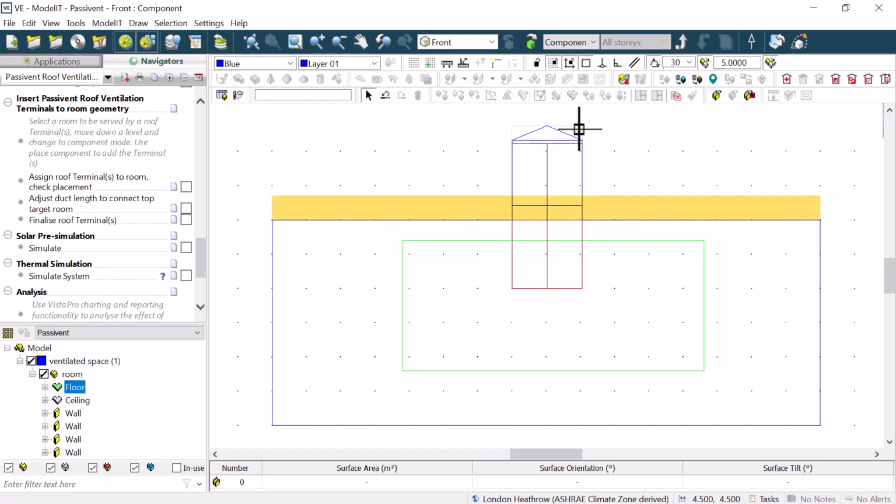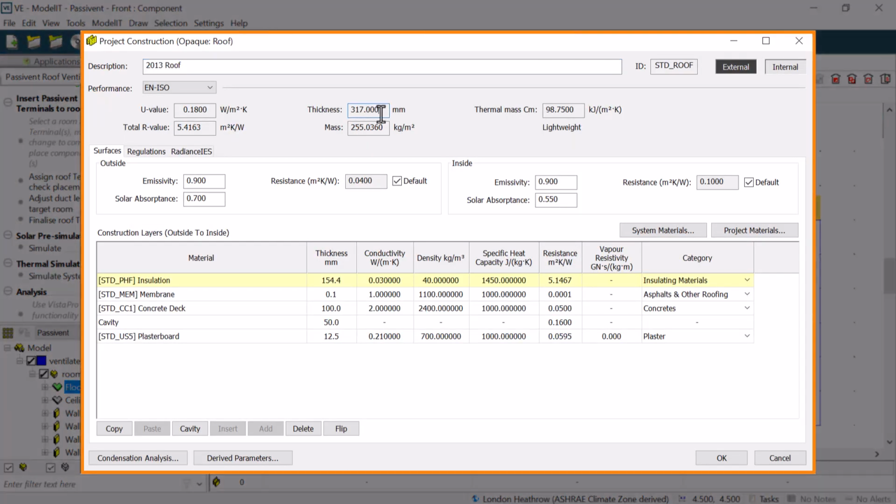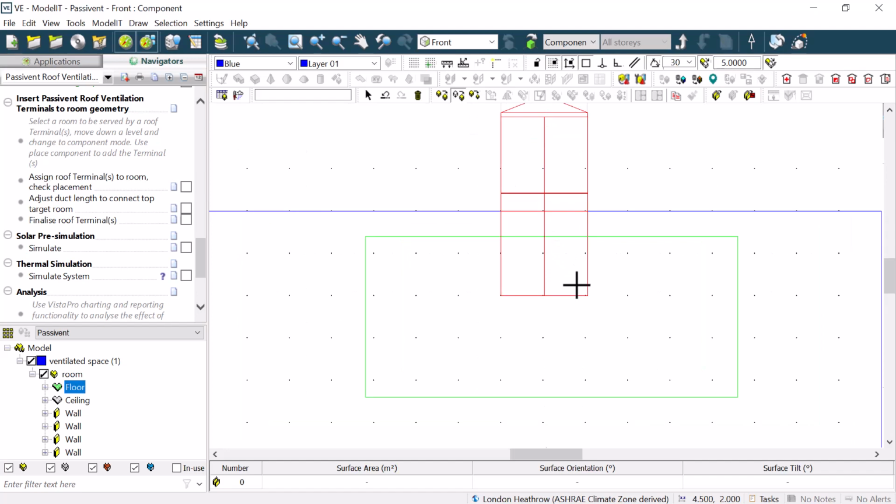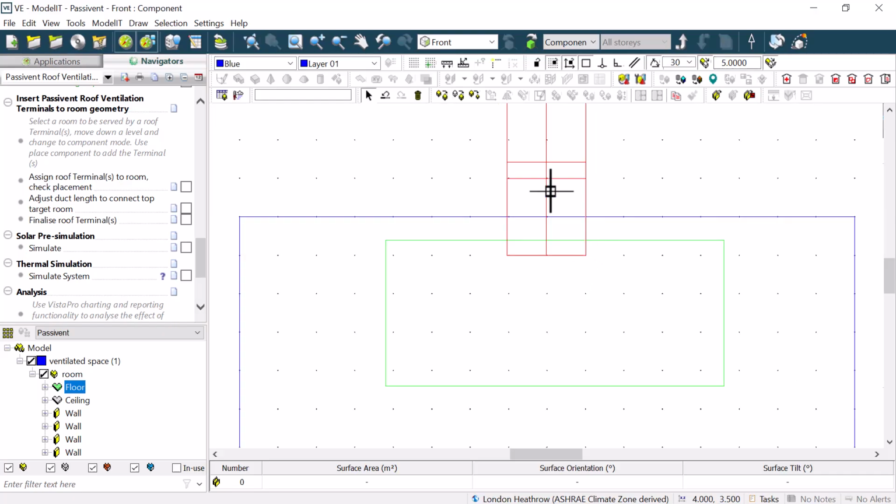At this point, remember that we cannot see the roof space or ceiling plenum above, but we do need to allow for it. This depth is based on the construction that we have assigned to this surface. We select the ventilator component and move it with the usual geometry editing options. Make sure that the locks are set appropriately for model endpoint, grid lock, etc. Then click on the Move Selection Set tool and align it so that the bottom of the terminal just overlaps